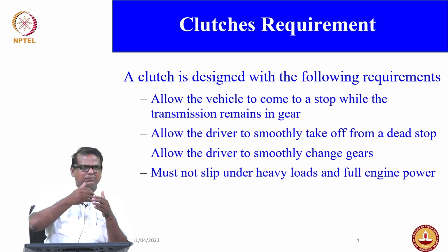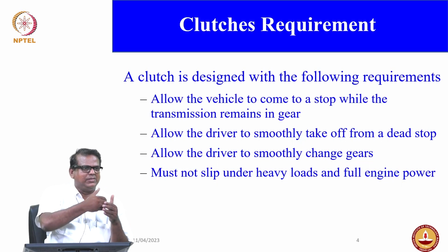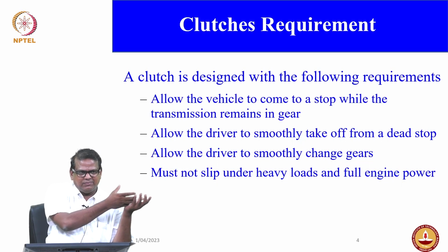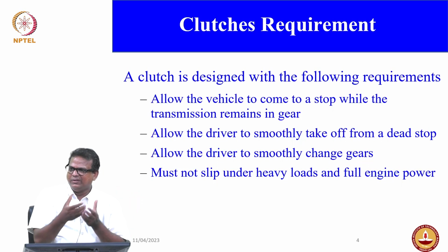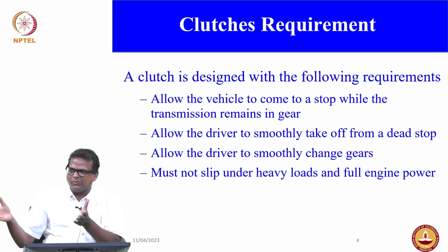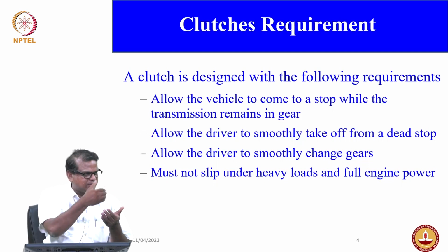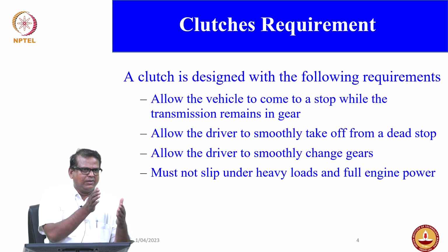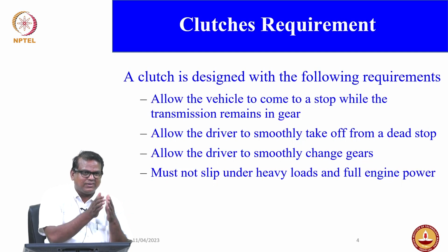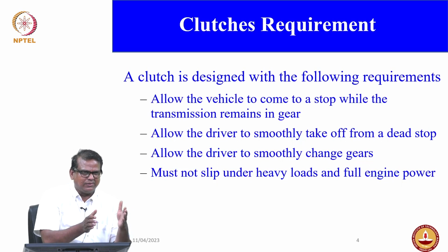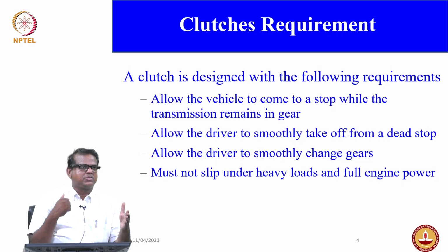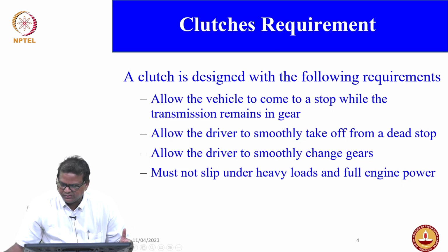That is the reason. For all the operations you need to cut the engine, because you can't have the entire power straight away transmitted. That would cause severe damage to your gearbox and other transmission systems, which you don't want. So the clutch purpose is that you disengage, or cut, the engine. Then you do the required changes, either to change the speed, or to start the vehicle or stop the vehicle, both ways. So that's the purpose of a clutch.